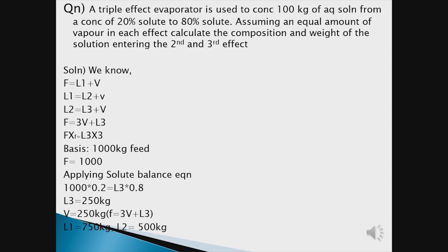So writing the molar solute balance for this equation, that is F xf is equal to L3 x3, and we are considering a basis of 1000 kilogram of feed, so F equal to 1000. Applying the solute balance equation, we could write F xf is equal to L3 into x3. We consider F equal to 1000, so 1000 into 0.2 is equal to L3 into 0.8.